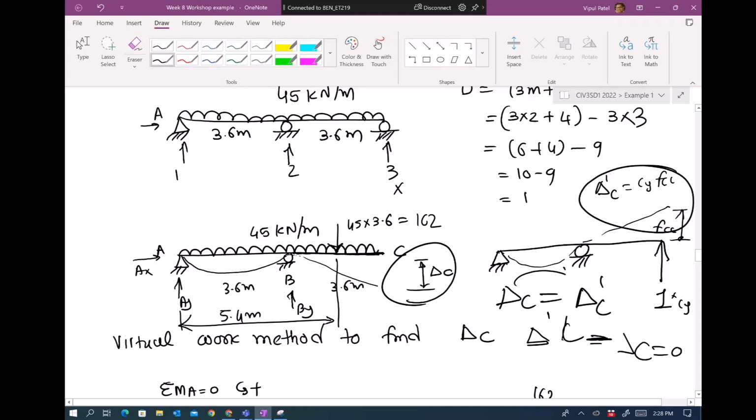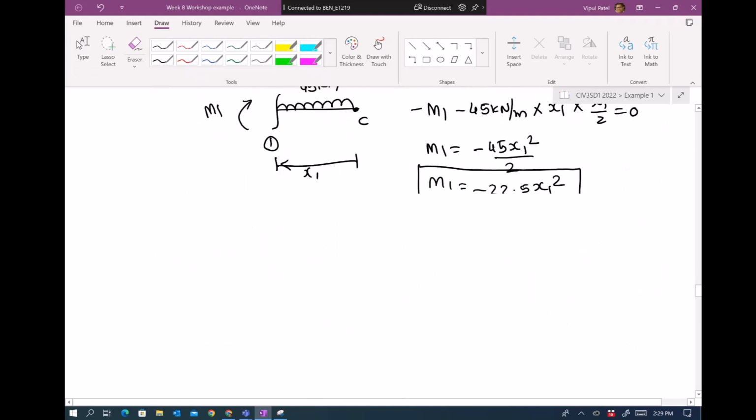Does it answer your question? So downward displacement minus, upward displacement positive. So therefore we have minus. Or you can say delta C equals delta C dash, because this displacement that we found equals this displacement. That is both equal. You can substitute a value and find the unknown value C1. Or you can do the compatibility equation, saying particularly at this point, downward displacement is negative, upward displacement is positive, equal to 0. All right, I'm not showing other methods now because I'm running out of time.